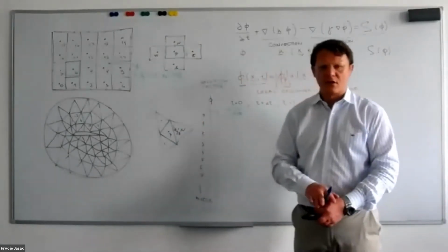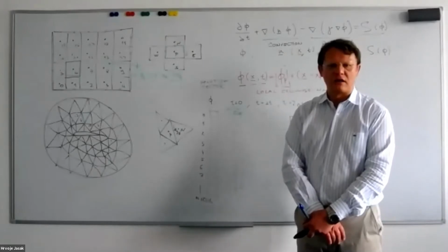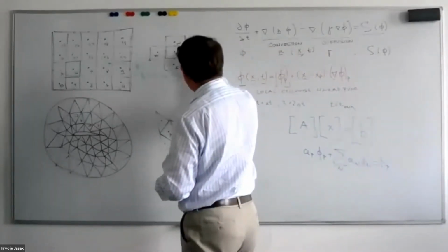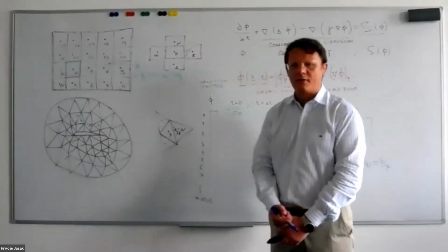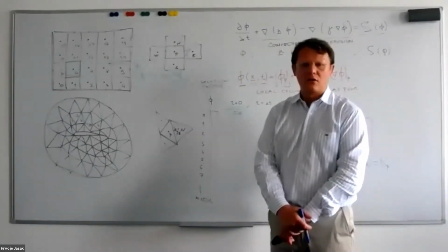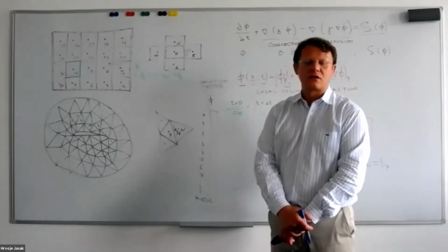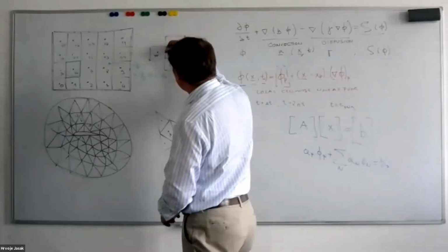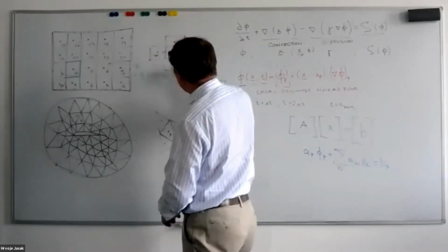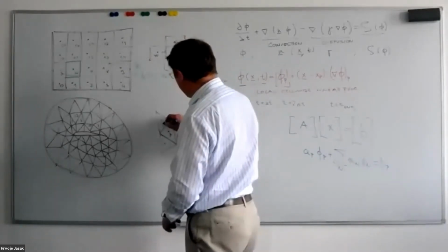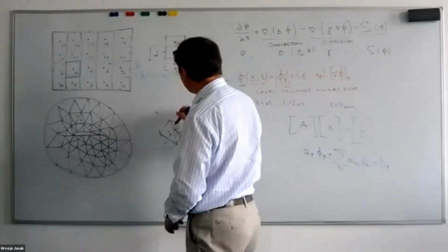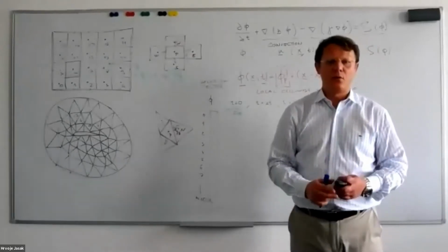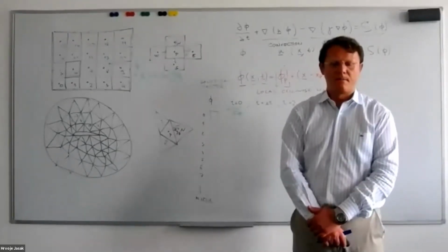With each face center, I will have an associated face area vector, SF, pointing outside of the cell of interest, and whose magnitude is equal to the surface area of the face. Notice that the same argument applies to quadrilateral cells, triangular cells, and the polyhedral cells that we're looking at.